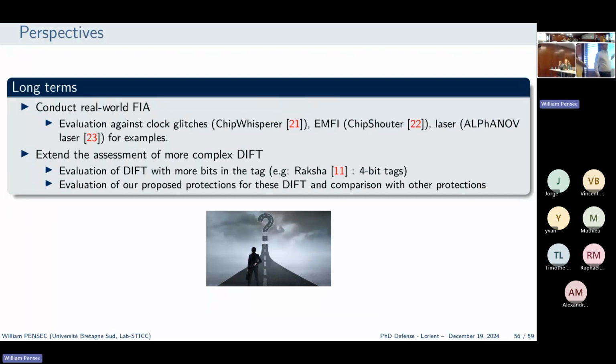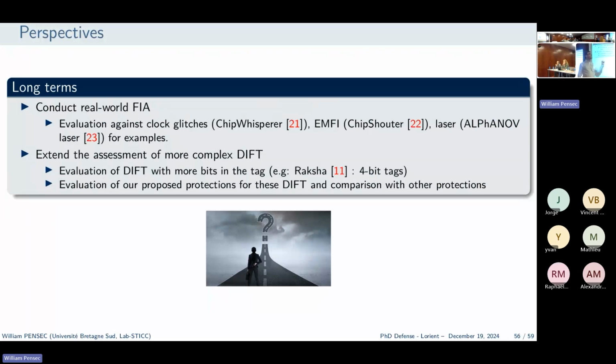Yeah. If we consider different ways of injecting faults, for my fault model, as I said, the best one would be laser, because clock glitches are too global on the circuit, so it would not be precise at all. Electromagnetic fluctuation attacks can maybe be good for injecting faults, but laser would be the most precise. And it has been shown in the literature that it is possible to inject faults in precise registers at precise times using a laser. This is why I'm citing the laser reference, because there are 2 and 4 spots. So with my fault model where I inject 2 faults at the same time, it will be possible with this kind of laser. So this is realistic, but of course you need an evaluation of the board, of the circuit, before injecting the real fault.